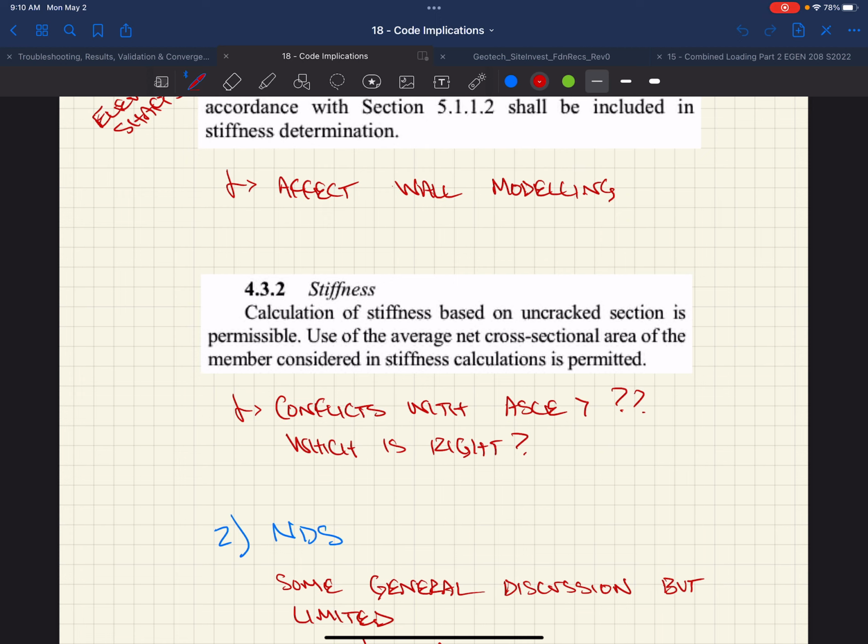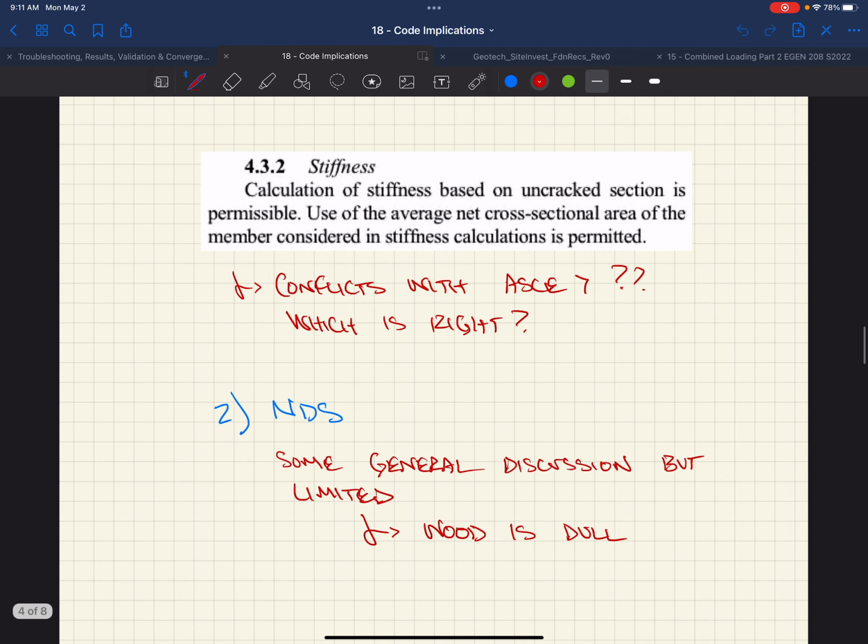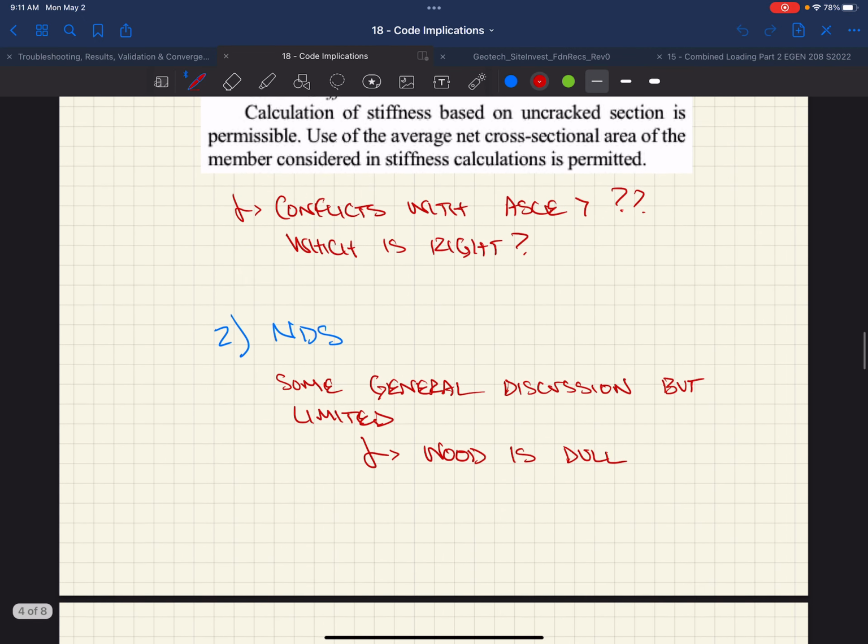And you might consider when you might not want to have that uncracked, right? If it's a shear wall, obviously it's going through cyclic behavior. You want ductile behavior, which means you want a lot of crushing and cracking of the masonry. You want yielding of the reinforcement. So for them to tell you that you don't have to use a cracked section modulus is crazy in that regard, in my opinion. Okay, but just something to think about.